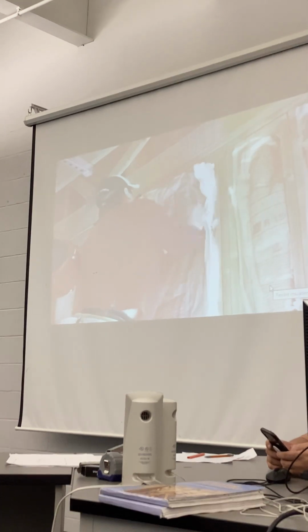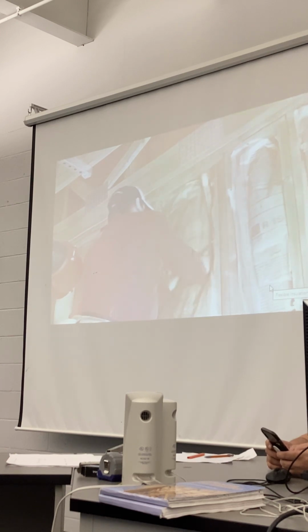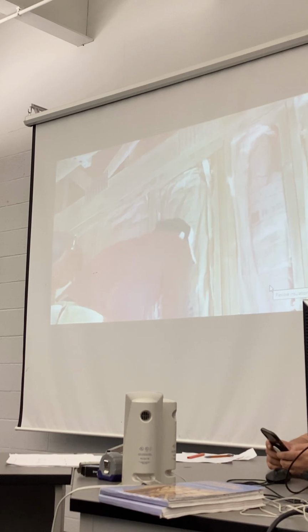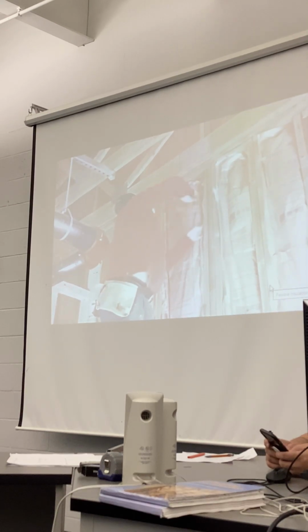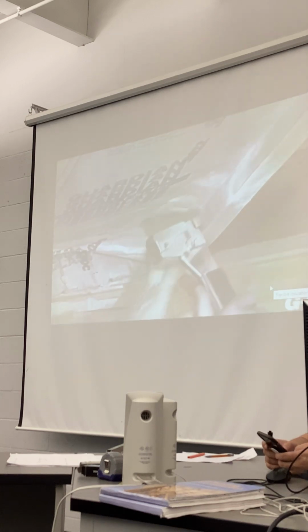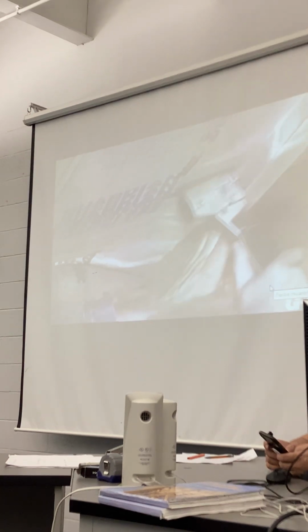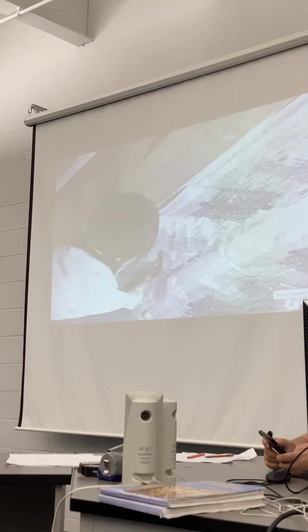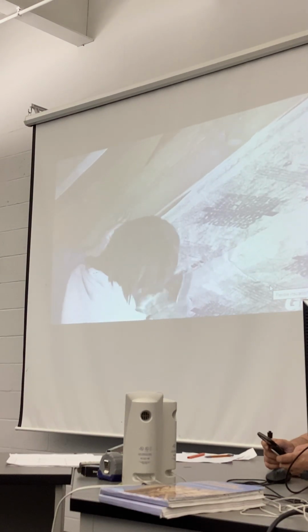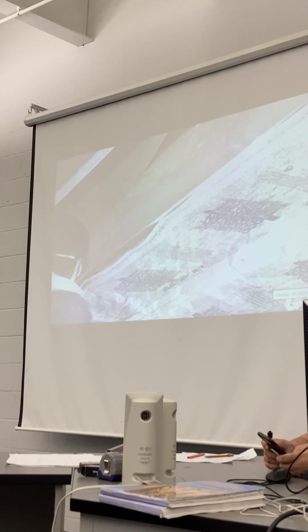When installing flexible insulation, fit the material between the studs or joists, starting at the top. Spread the paper edges out so they lap inside or over the studs or joists. Some contractors fasten the paper edge of the insulation to the inner sides of the studs. Others lap the paper over the outside edge of the studs for improved R value.